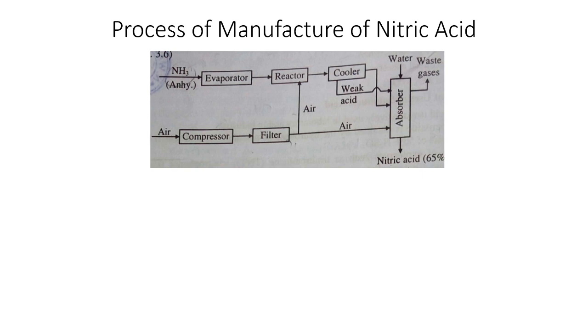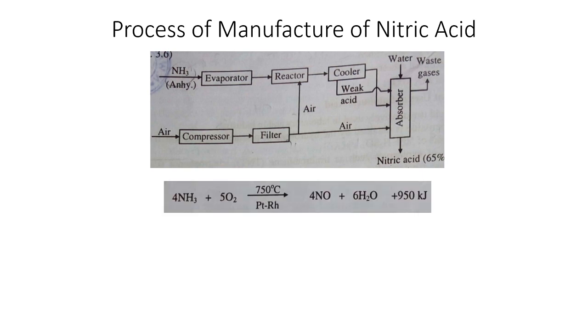And then there is an electric current made available for a heating arrangement for the starting material, so that the reaction will start. Though the reaction is exothermic, for the initiation of the reaction you have to heat it using an electrical heating arrangement. Once the reaction starts, the reaction itself is exothermic, so you can maintain that temperature from the energy coming out of the reaction.